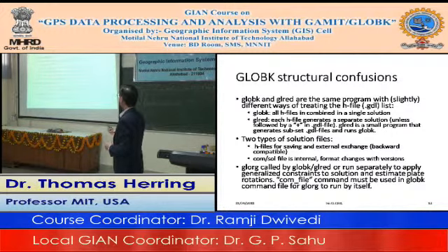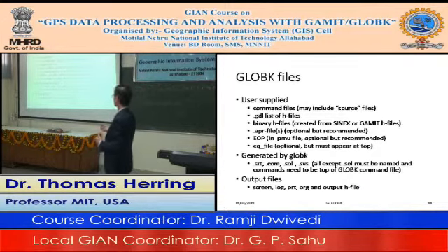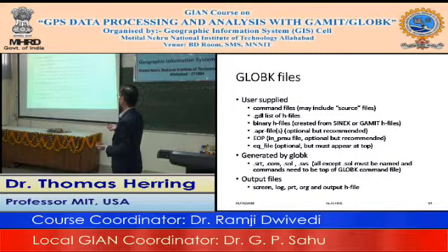So the GLOBK command files, the things you have to supply. You have to supply the command files. As I said, we have templates that you'll start with and modify, but you have to develop that. It's a bit like having to do the sites.default file yourself. You have to supply the GDL file with the list of H files to be processed. The binary H files themselves need to be created either from SINEX or from the GAMIT H files. So that's the minimum of what you need to do.